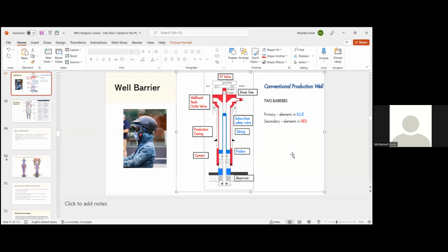Okay, right. But if you are flowing the well on the production header, your fluids will be getting inside the flow line and the header, and it will not be contained under the surface safety valve. So I think, in my opinion, this is valid for just a shut-in condition. And the flow condition will have other barriers like the flow line itself. Yeah, the other barriers of the flow line is another story. We just want to make sure that the fluids flowing from the well are controlled. But the flow line to the facilities is another story as I see it. Right. Or do you guys deal with it in a different way in GAPCO? Yeah, we have a different methodology. We have some details about this issue, but I think you are right about this point.